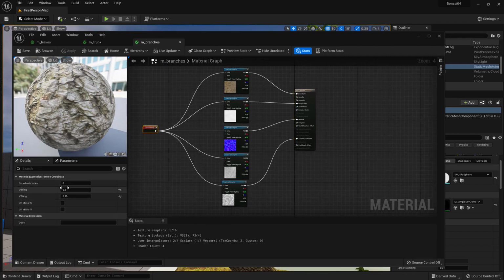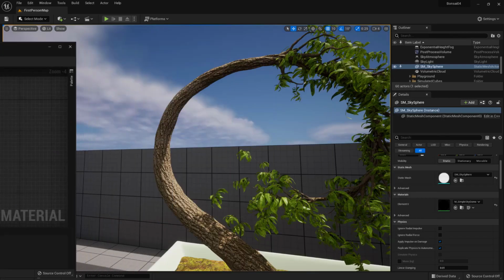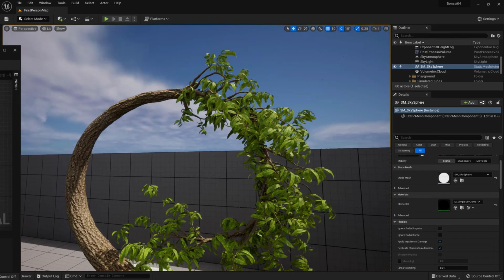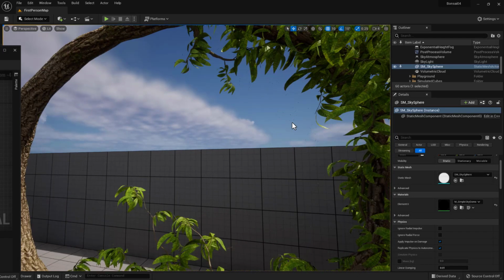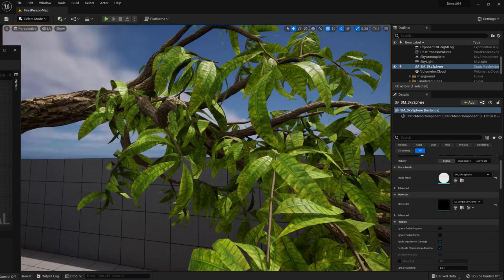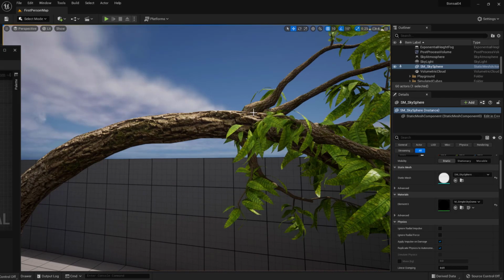And then I changed the texture coordinate because it was way too tiled for the little tiny branches. So right now I have it at U 0.5 and V at 0.25. And so if we go into the actual branches, I don't love it, but it's not bad. I mean, it's sellable if you're not right up on top of these things. So you can see it actually looks like the same as this, but just sort of tiled more.